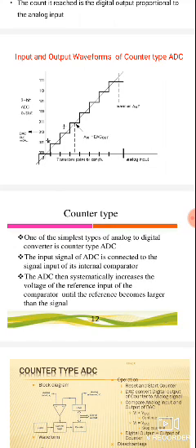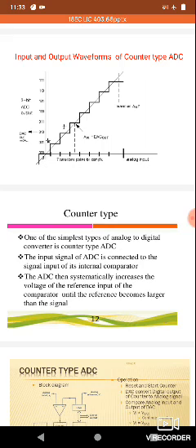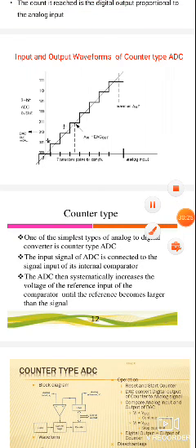So this is the analog signal. The analog signal will change, and the changing value will be represented in digital form. This is the DAC output, a 3-bit DAC output. Next, there are 7 transitions, starting from 0 to 7. 0 is the binary 0. Next, analog input 1 is indicated by 001, then 010. So this is almost 7 steps.